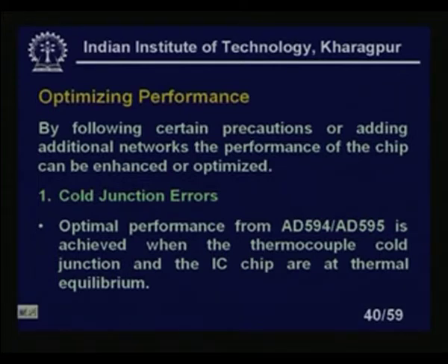So usually I put the AD594 and AD595 very close to the isothermal junction, that means where I am connecting the copper wire to the alloy wire of the thermocouple.